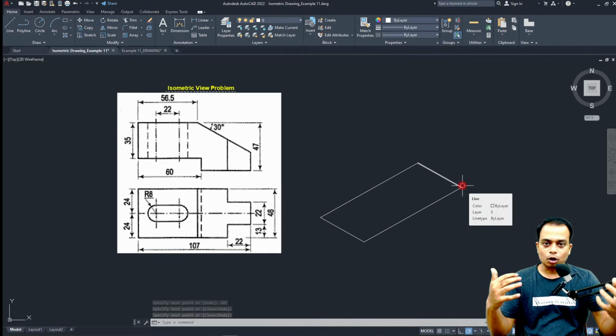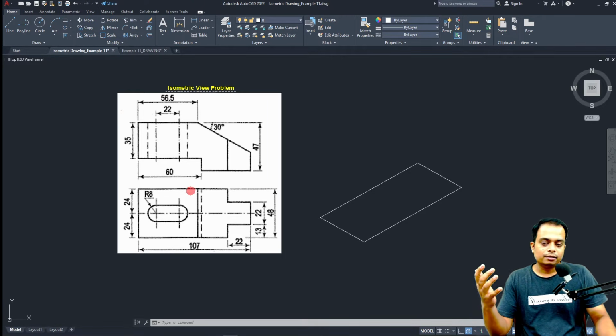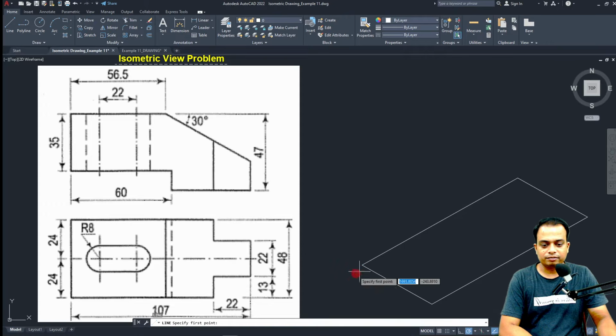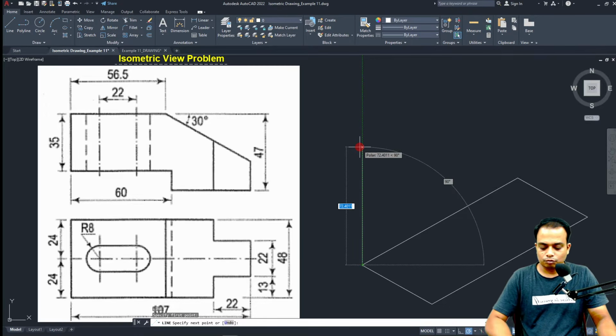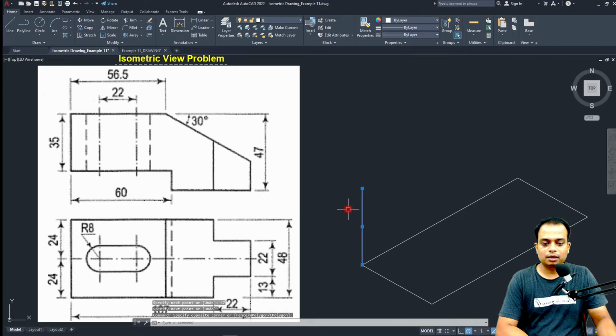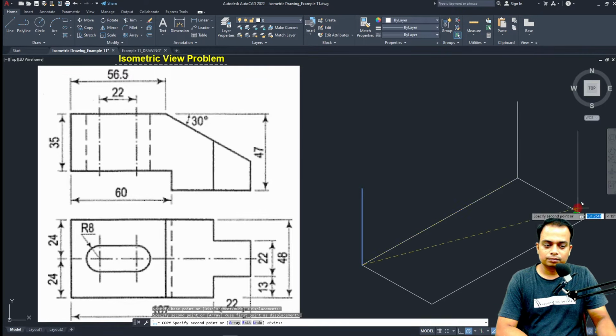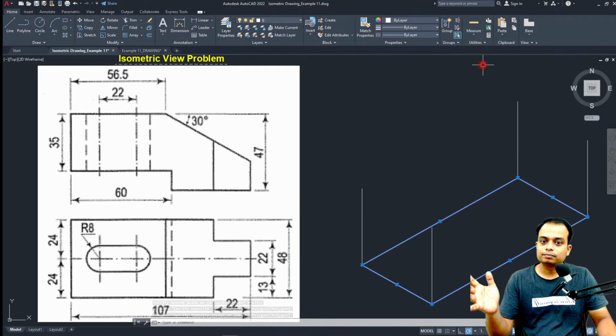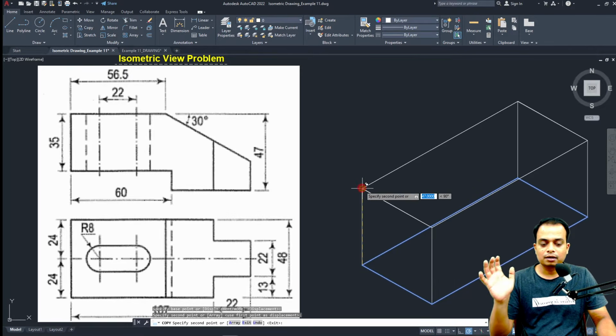We are now going to create a box inside which we'll be fitting this object, right? So what is the height? Maximum height I'm talking about. It is equal to 47. So give it some height, 47, enter. Now click on this, make a copy. This is the base point. Click. Now select these, and for all you guys who are doing this manually, you can join all of these points. The rest of the guys doing it in AutoCAD can follow the copy command.